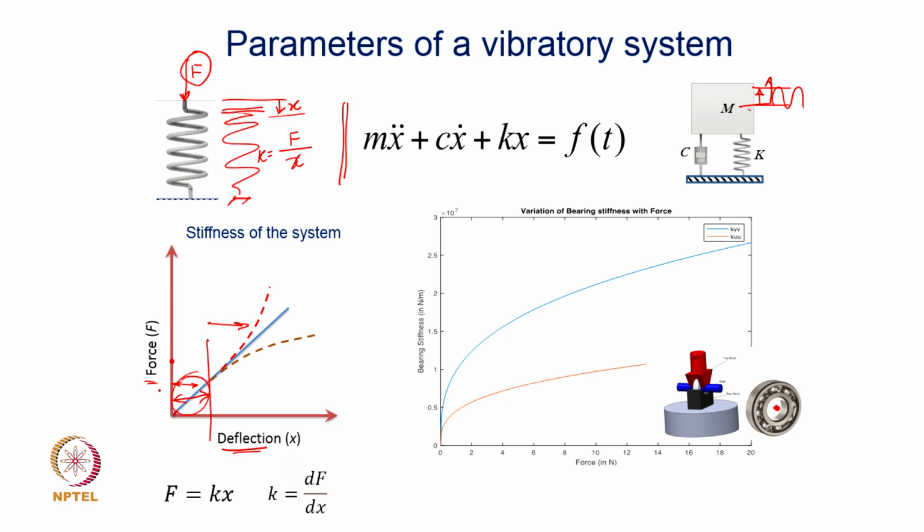Okay. And so, small amplitude vibration pertains to this range of linear force deformation or force deflection relationship, it is perfectly valid to assume a restoring force which is directly proportional to x and k being constant, and therefore, the small amplitude vibration takes care of linear vibration analysis. And therefore, although it is valid for small amplitude vibration, you can definitely use this equation for your preliminary analysis.